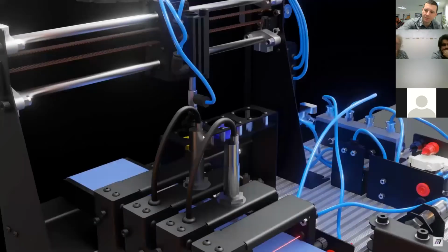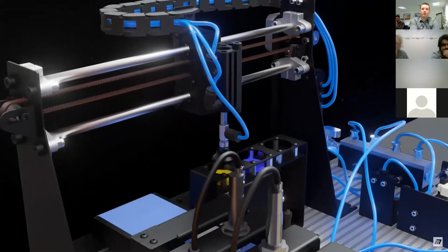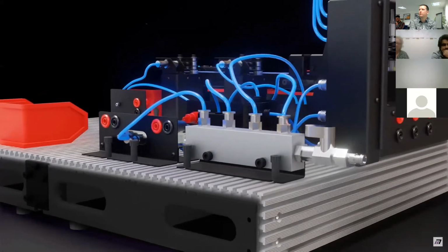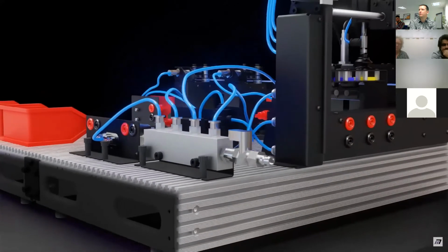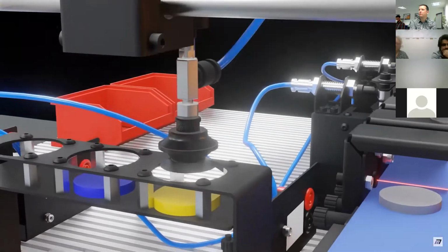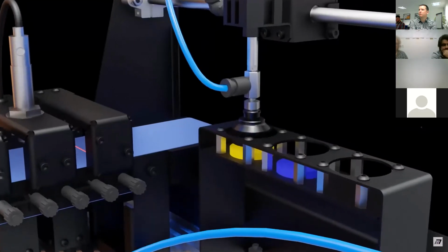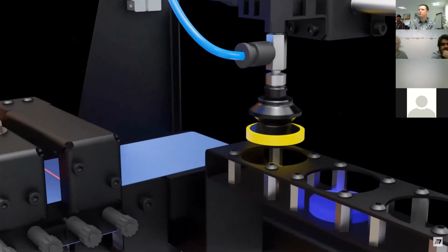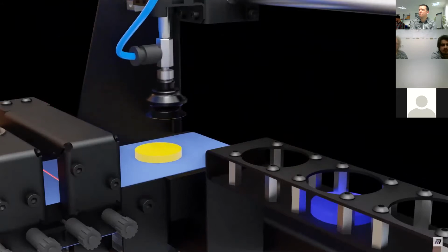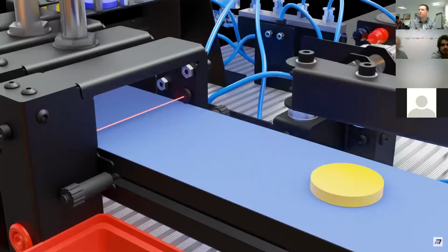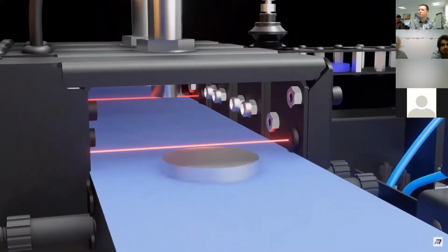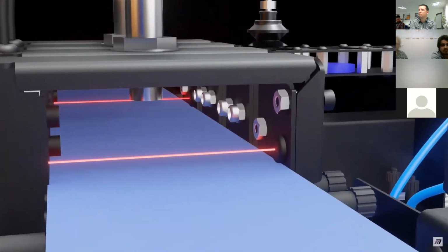The smart factory gantry makes use of a limit switch, stepper motor with 3 inputs, and a plunger. Students follow our worksheets to control the stepper motor and drive it using a PLC, and in turn control the plunger mechanism. The suction device then delivers parts onto a conveyor belt, which is fitted with inductive and capacitive sensors, allowing parts to be distinguished from each other and placed automatically into bins. 2 laser light gates are also fitted for triggering and timing of the conveyor.